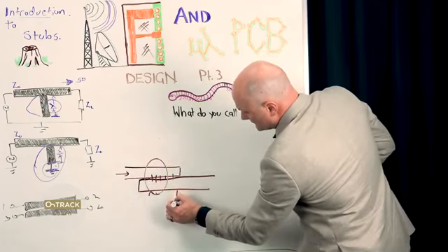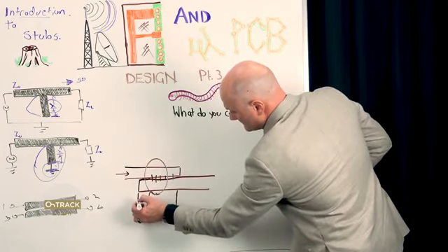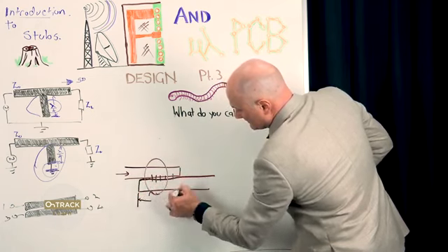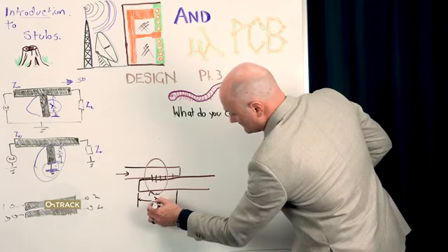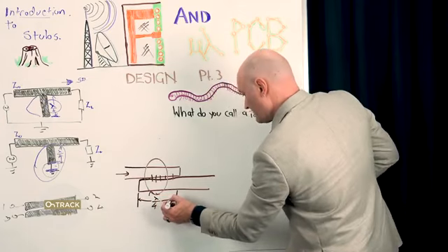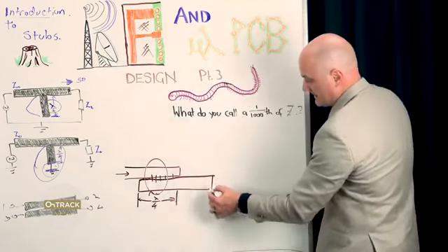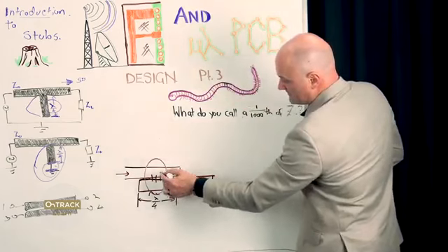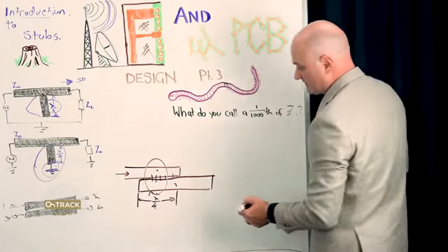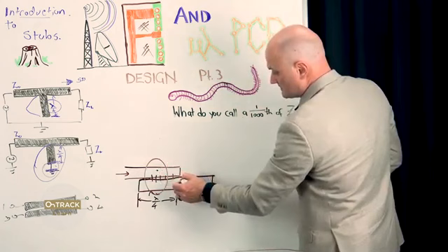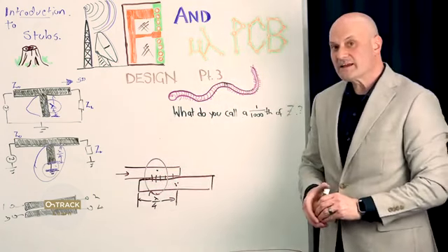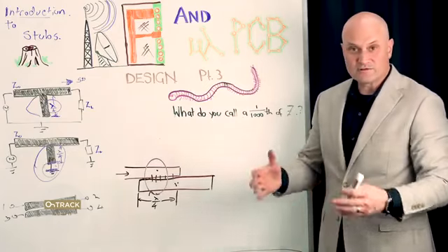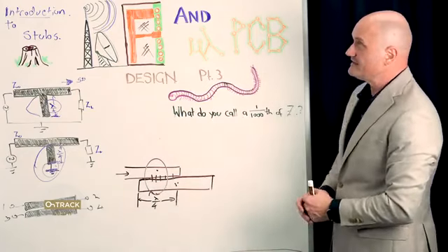And usually, not always, but usually, the length at which they're coupled is a quarter wavelength. Here's that number, quarter wavelength, showing up again. And this copper then resonates because it's coupled with this one. Energy's transferred from this one to this one. But we'll talk about that in more detail with an actual worked through example in the next video.